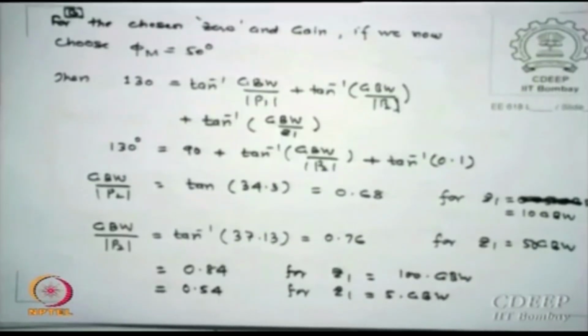So you will find that this does not change very much, but something else changes, because of larger phase margin, GM may be different or the CC value you choose may be different, and that may create further problems in some other poles. Slew rate for example. So do not think that this small change means small change everywhere; maybe 10 times somewhere else. So the decision is how much.